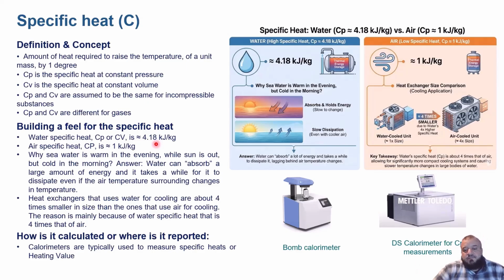You see, there's a CP and CV. And the difference between them is that process I just explained. Actually, if it's a liquid, like water, or a solid, like a piece of metal, it's very reasonable to say, well, it doesn't matter if pressure is constant or volume is constant. These are incompressible. It's the same number. A CP is a CV is a C.